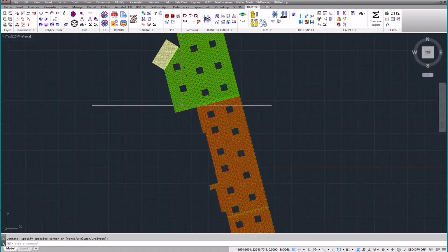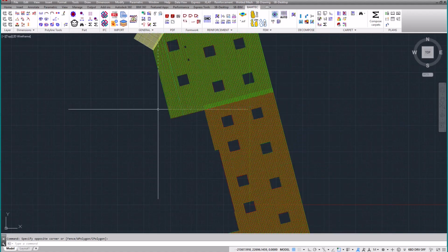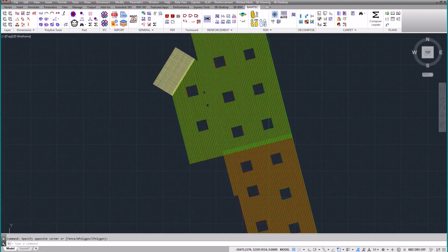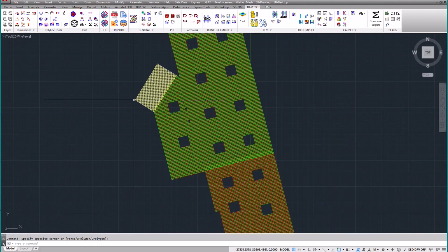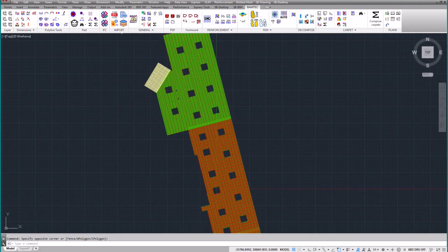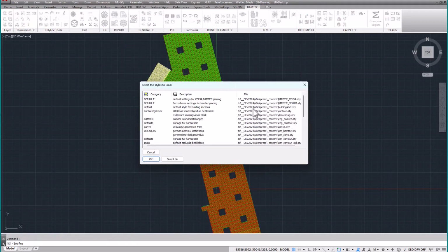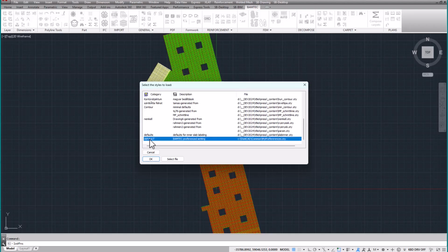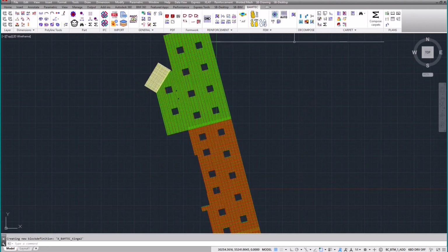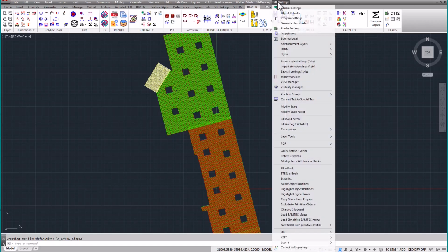Here we can see all the straight bars. The program automatically filters out bent bars. We can also see that several different bar directions occur in this drawing. Next, we load our preferred styles and settings using this function. This DXF file is currently completely empty and contains none of the settings we previously created, so we load them now. Our preferred settings can be created using the Export Styles function.